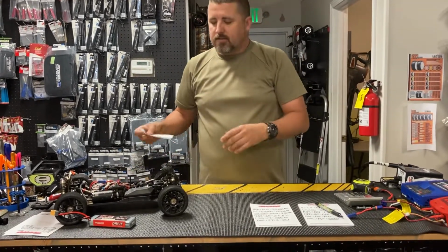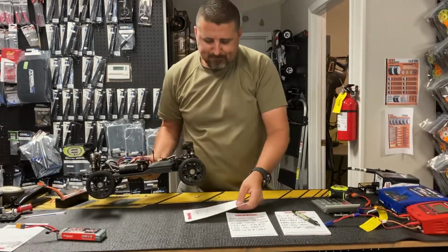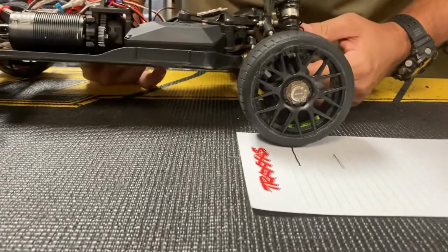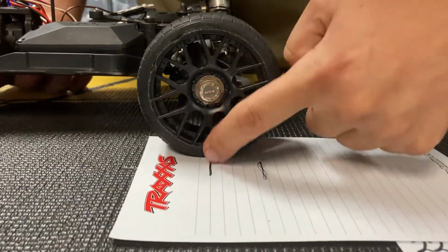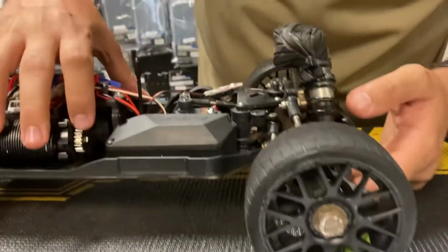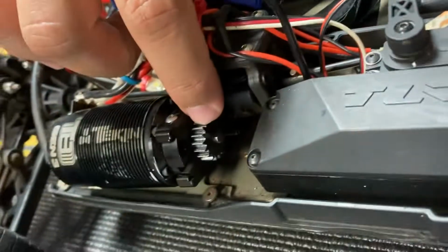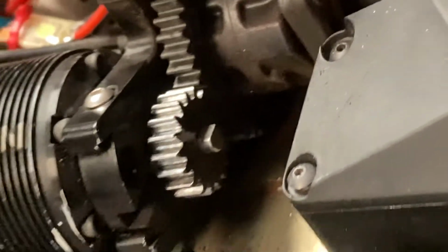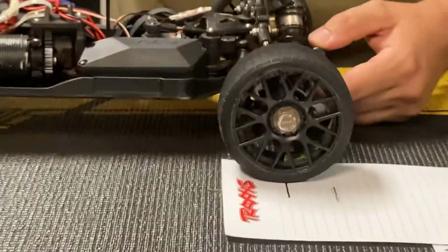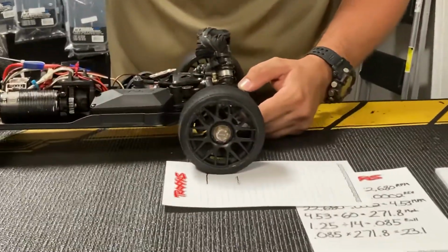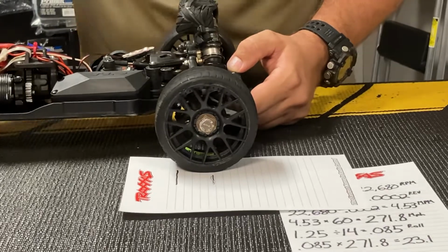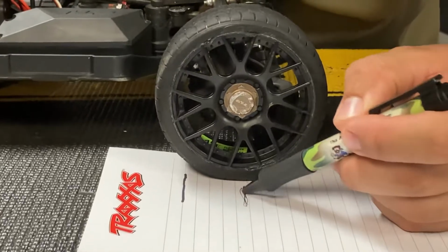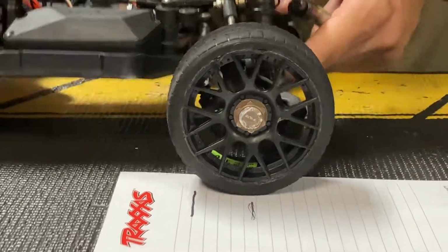Now, there's a very easy way to do this, and I'm going to show you guys this right now. Take a piece of paper, draw a black line on that piece of paper, and line it up so that that black line is straight down your axle, just like that. The next thing you want to do is put a nice mark on your pinion gear that you can see. In this case, I'll put a silver line on my pinion gear there. Now I'm going to start rolling my car until that silver line goes all the way one complete revolution. And once it does that, I'm going to come back and draw another line on my paper right at that point, which is what we've done here.